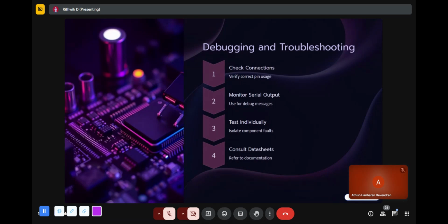And if nothing works, you can check the entire thing separately. For example, if you have a system of 5 motors and nothing is working, it will be either the issue of the power supply, the motor driver, or the motors separately. So the last way is to test the motors individually. You directly connect the motor driver and the power supply, and test each of the motors. That is the last way to find errors.